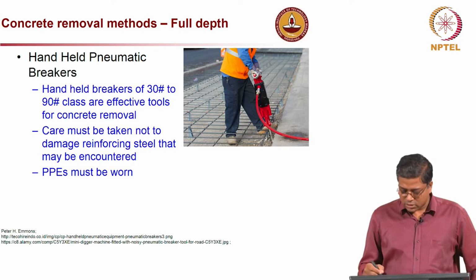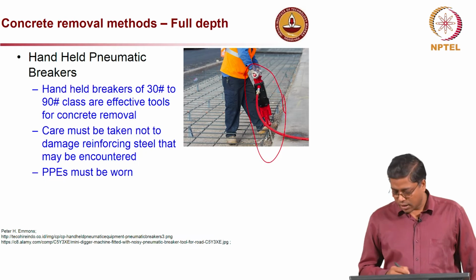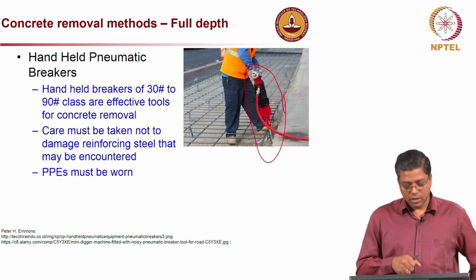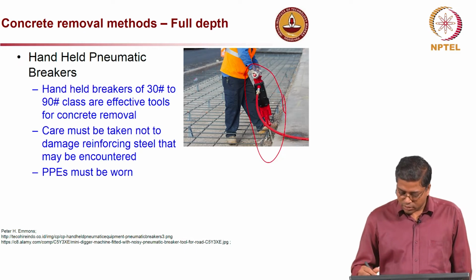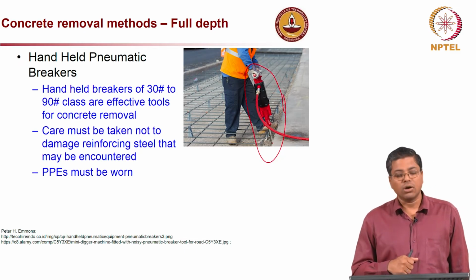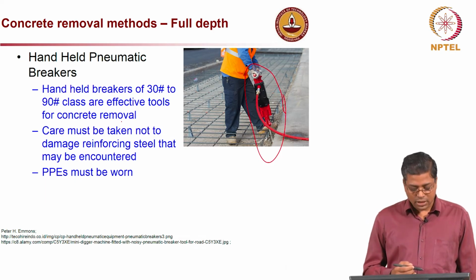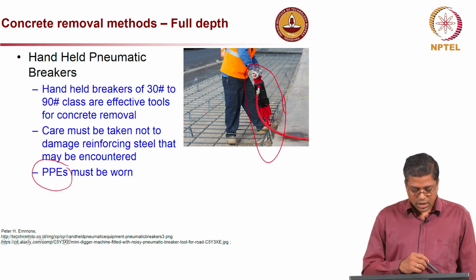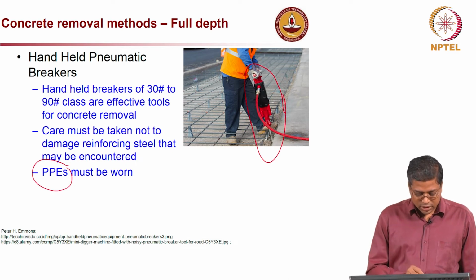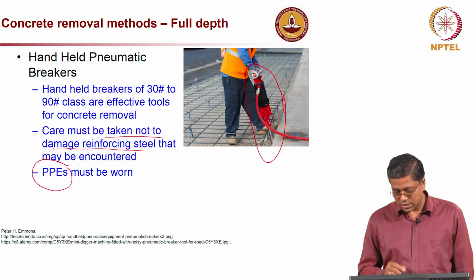Now this is also a widely used tool in India, we usually call it a jackhammer, essentially a hammer which keeps on hitting the concrete hard, and hammers of different capacities are available. But again PPEs must be worn when we use this. Another thing is that it should not damage the reinforcing steel that is inside the concrete.